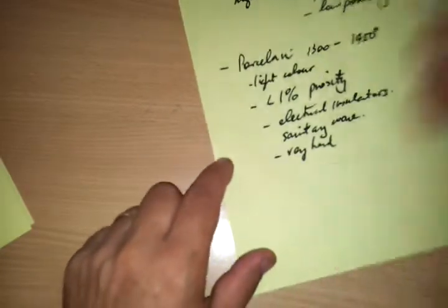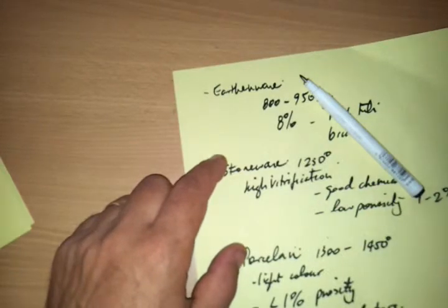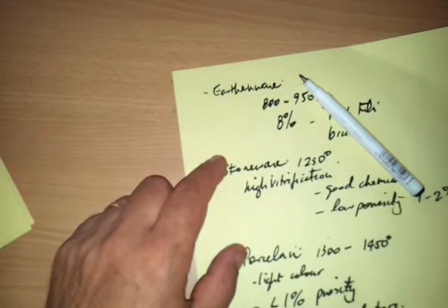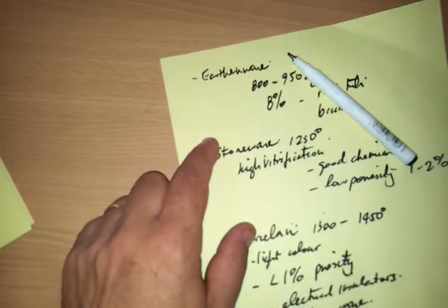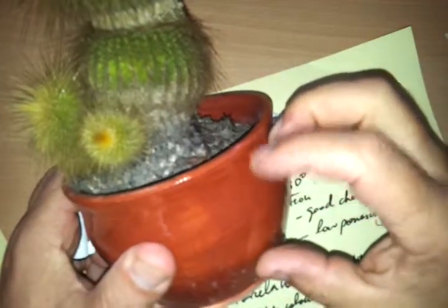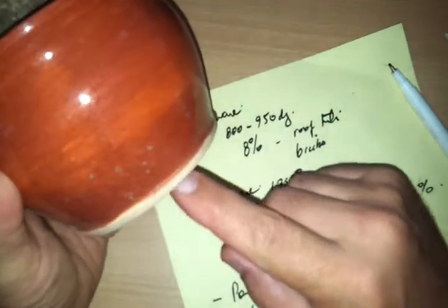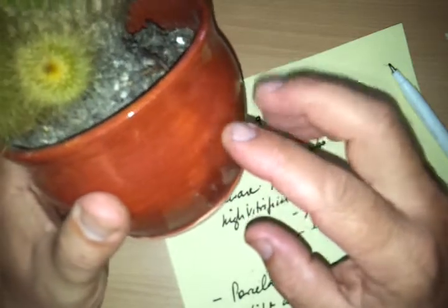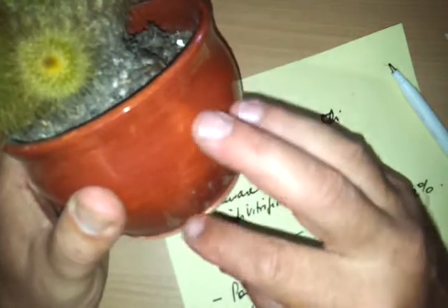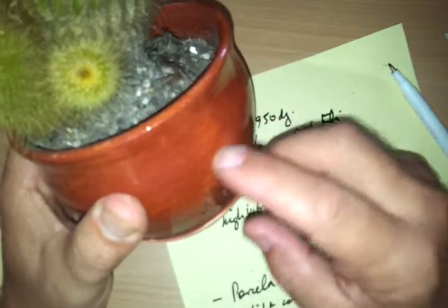Okay, and lastly we've got glazing. Now sometimes you might have an earthenware object like, let's see if I can find one for you. Yeah, over here. Without damaging my hand, because this is a cactus. You might have an earthenware object, so it's only been heated up to around the 800 to 950 degrees, but at the same time you want to reduce its porosity and maybe change its appearance, so you can apply a paste glaze, which would be a silicate form, usually with some colouring pigmentation from metal oxide.